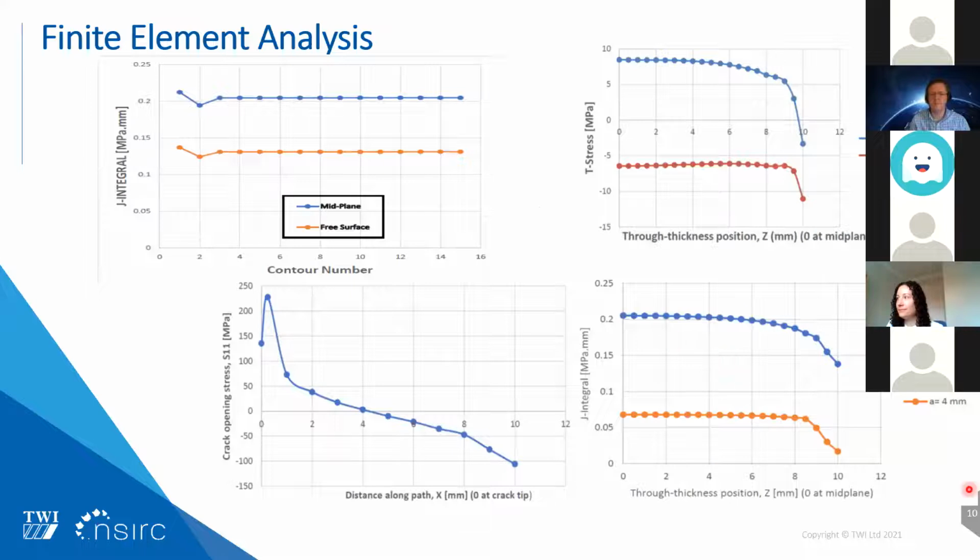Now, so far some FEA has been done using the three-point bend specimen to illustrate the contour independence of the J integral and then the T stress.